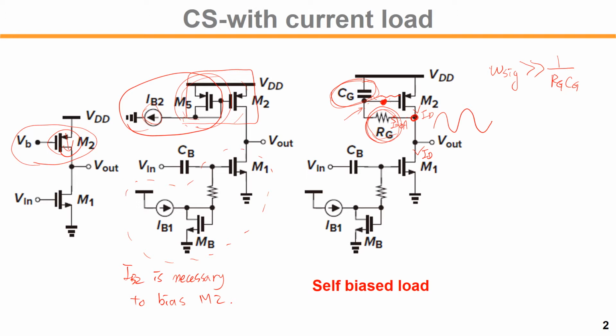What happens if the signal moves the same as the drain voltage? Then it becomes, for ω much less than the bandwidth there, the signal moves the same way, the same voltage is shared across the gate and drain, so it becomes equivalent to a simple diode-connected load.